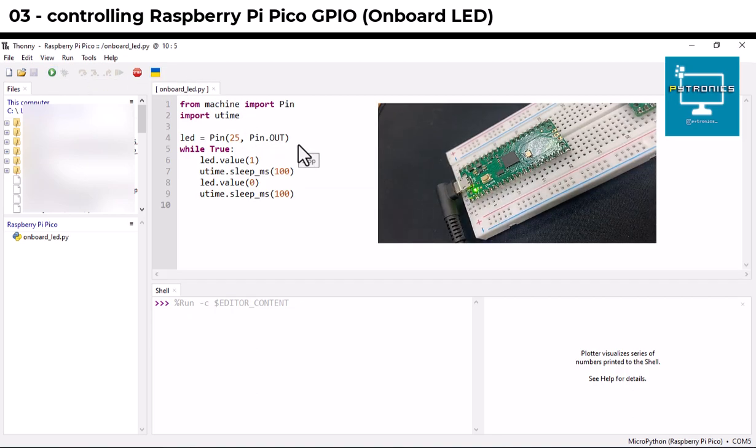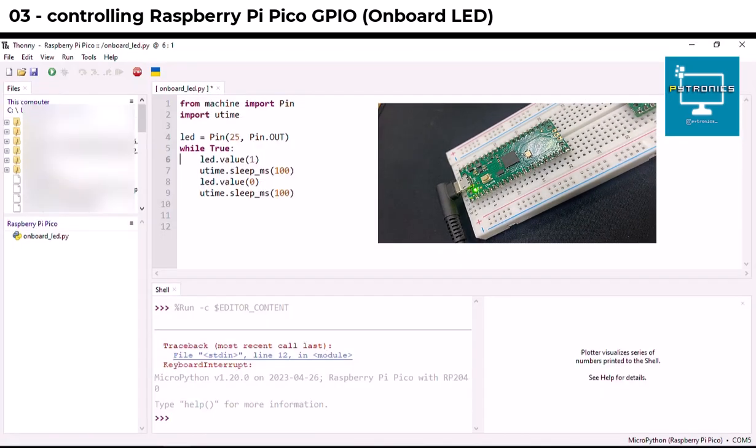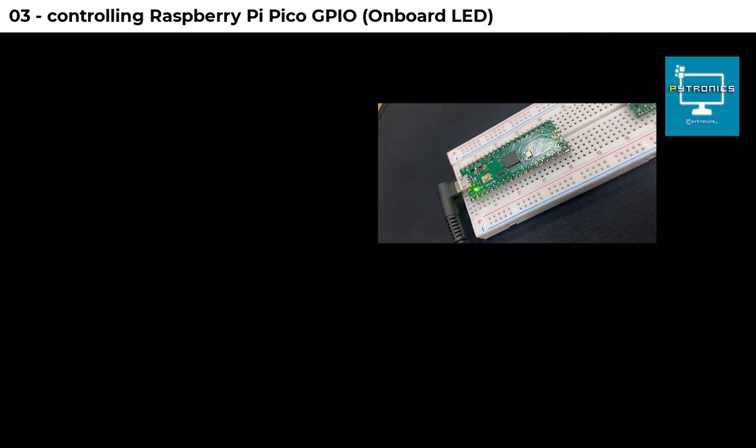And this is how your Pico reacts after you run the program. The onboard LED will switch on, then wait for 1 second, and then switch off and wait for another 1 second. This program will run forever, or until you stop it.